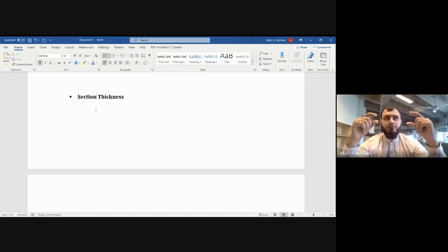Sorry, this phenomenon is called hot spot. Hot spot is the defect in the casting when there is asymmetric thickness in the cavity.